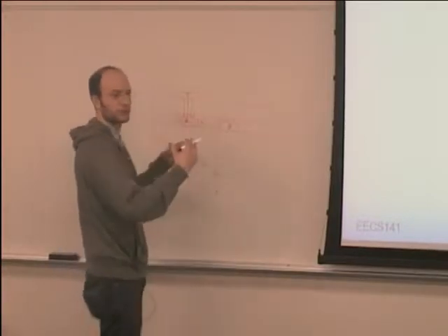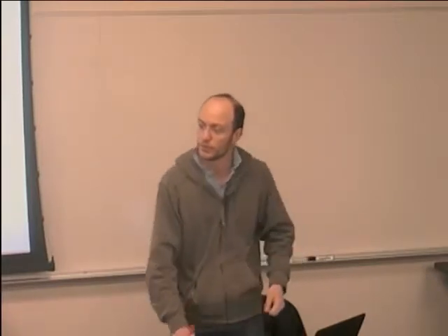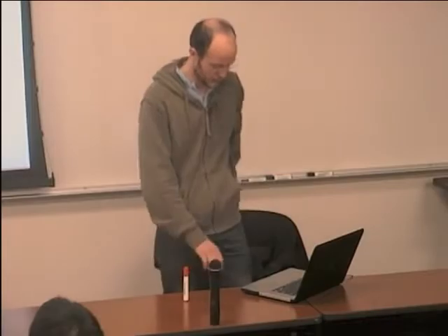Okay, and typically you can choose when you extract whether you want to get only capacitors to ground or also capacitors between different wires, right? And the trade-off there is that if you include all the capacitors, your simulation is more accurate, but there are more capacitors, which means that it's slower too, okay? So you should know all this.